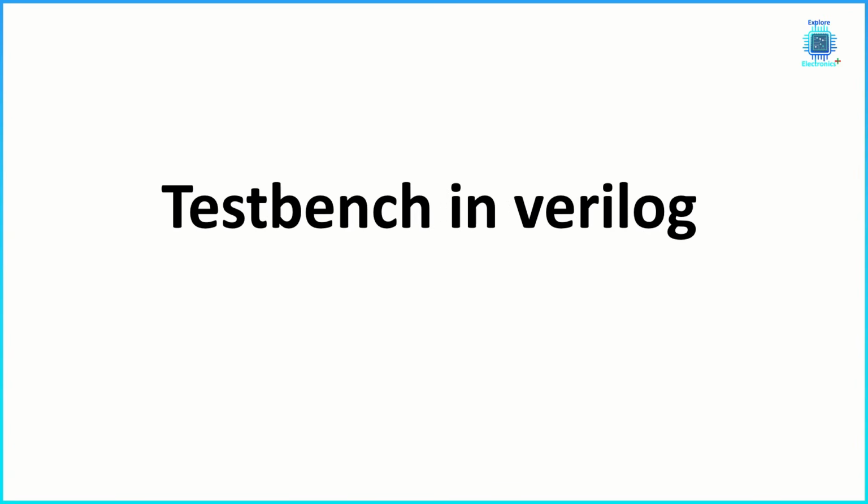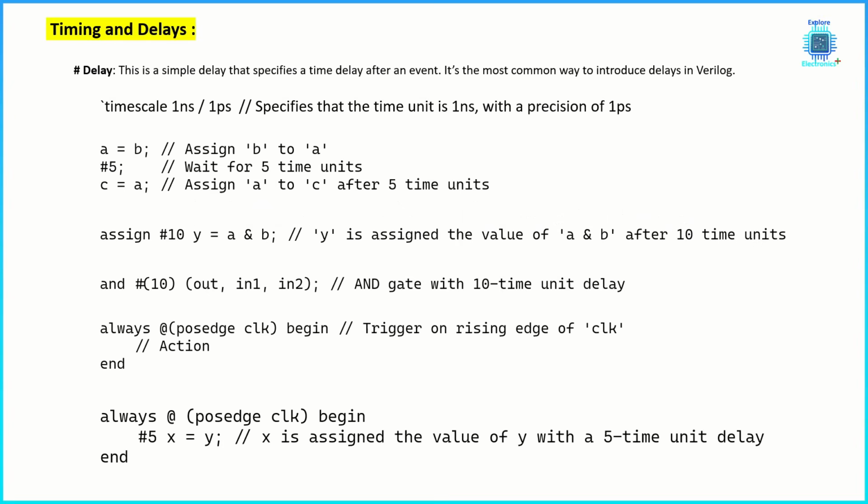Then the next thing is how we are going to write a test bench in Verilog for these designs. Test bench is a very crucial component in Verilog to verify the functionality. So let us understand test bench aspects now. In the test bench, the very first thing is we need to write a time scale. Why do we need a time scale? In the test bench generally we will be assigning the values. Suppose if we take a full adder example, we need to assign a value for input A, and then we need to assign the input B, like this.